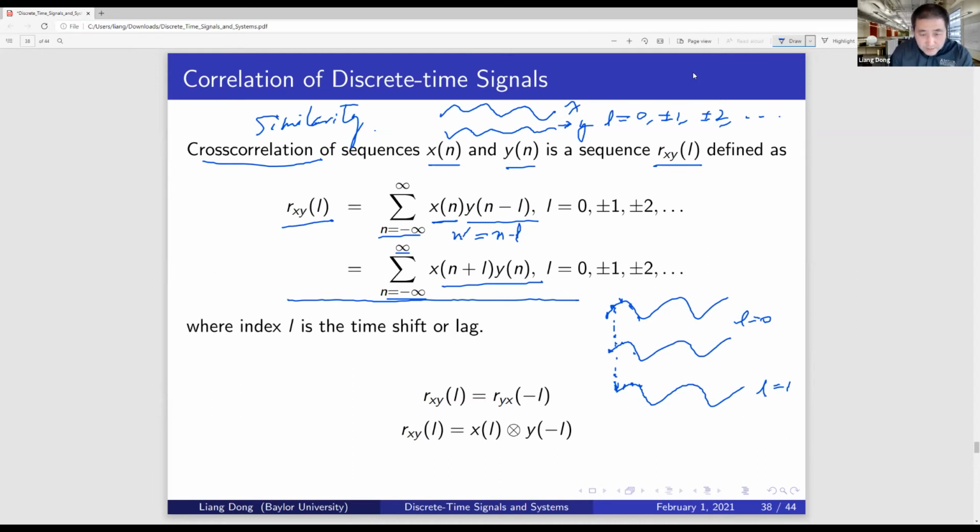Now, because of those two steps, the first one and the second one, we know that this cross correlation can be written in this way. The cross correlation of signals x and y with lag L equals the cross correlation of signals y and x with lag negative L. You just make x compare with y, so instead of shifting left, you shift right in the other direction. So it becomes negative L. And you can plug in here as well. So we have that.